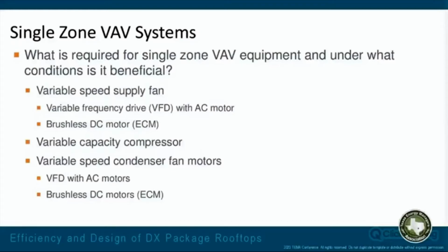Now you're going to have a pressure transducer on it, and you're going to control the condenser fan speed in order to maintain a much more constant condenser pressure. It'll also help with avoiding some noise complaints if it's sitting outside a window with occupants nearby, because it will be a consistent sound level, not that on and off that you're going to get using a fan cycle switch.